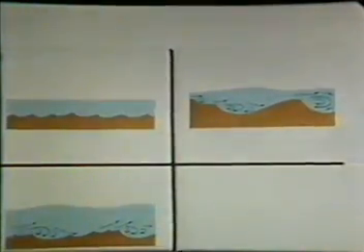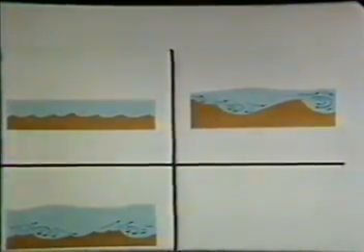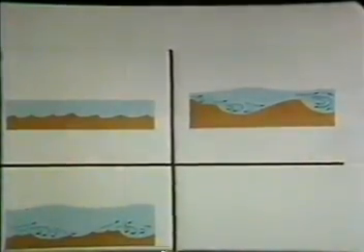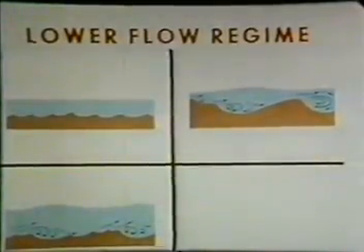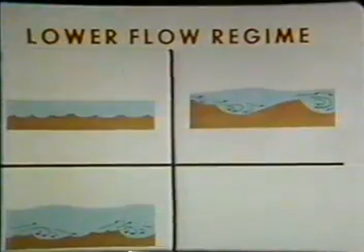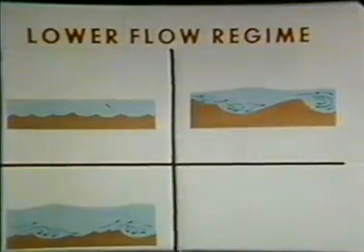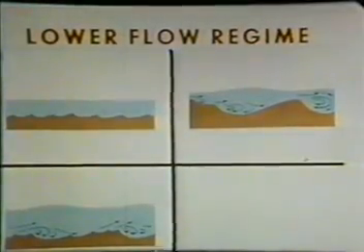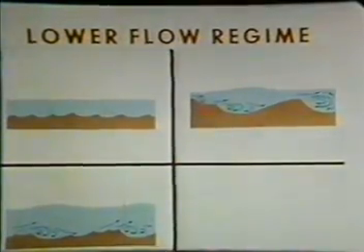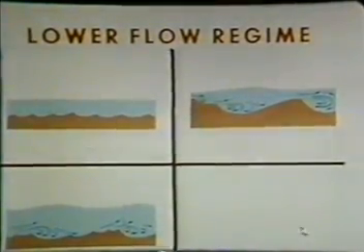The first three bed forms are grouped together insofar as roughness, form, and sediment transport are concerned. They have been classified into the lower flow regime. In this regime of flow, the water and sand waves are out of phase, just as in tranquil flow with a rigid boundary. Sediment transport is relatively small, 1 to 1,500 parts per million, and resistance to flow is large. Manning n will vary from 0.018 to 0.040, and Chezy C from 44 to 60.